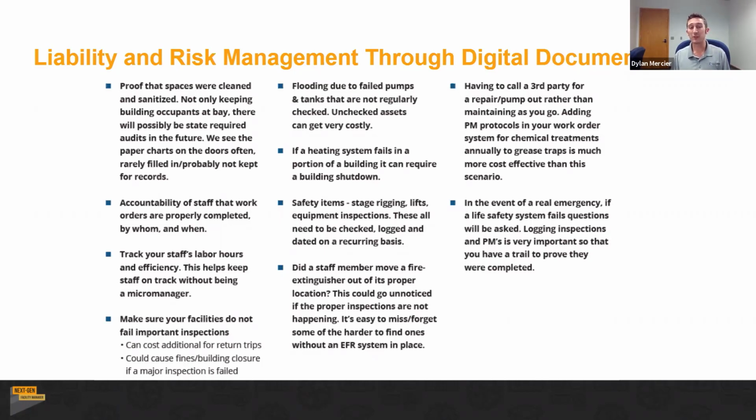Little things that could be major safety concerns that we see time and time again are fire extinguishers that get moved. Typically, they're in those closing cabinets and they have a home, it's marked, there's a sticker, but we see it often either in classrooms, mechanical spaces, stage, catwalks, things like that, where they're a little more freestanding, and sometimes they get buried with equipment. Boxes of material may be blocking it. Stored items may prevent those cabinets from being opened. And making sure all those are getting caught on your walkarounds is very important.